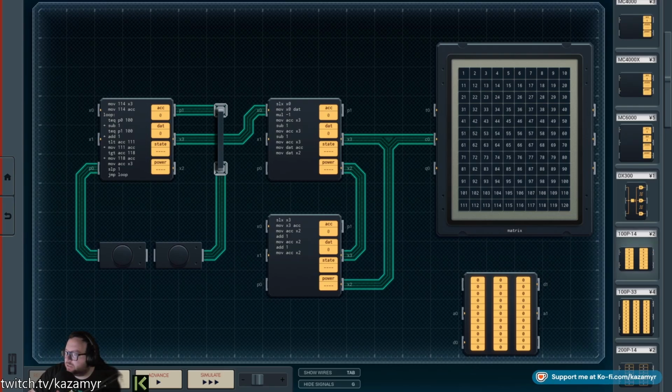Yeah, so those are our logic bits. Anyways, what do we got? We got random access memory. This component here, we've got A's. All memory cells initialize to a value of 0. All memory pointers initialize to point at the first memory cell, address 0. Memory pointers can be read and written over X bus with the A0 and A1 address pins. So those are read and written.